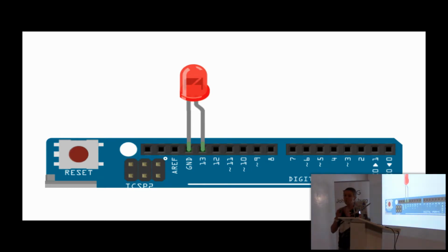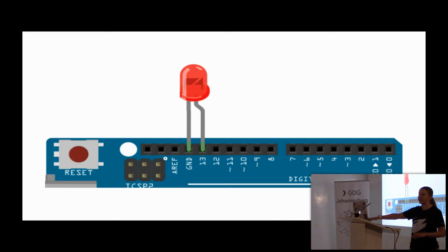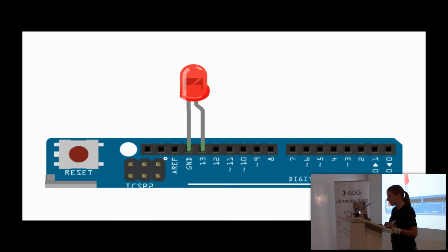The reason it works is because these development boards, the Arduinos, Raspberry Pis, all of them, actually have some built-in resistance. So that's why it's not actually going to blow the LED. But every now and then, the built-in resistance on these boards can fail, and then the blue smoke inside the electronic component leaves the component, and it doesn't work anymore. And you think there's something wrong with your code, because the first thing you think is, there's something wrong with my code. It's not. It's just because the component is broken. And over there, I have a bunch of backup LEDs in case something goes wrong.